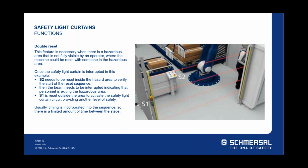So what double reset does is it requires you, after the light curtains are broken, to reset this function. You have to hit S2, which is inside the hazardous area. You have to leave that area, so the light curtain has to see you break those beams, and then hit S1 or restart 1 outside. This all has to be done within a time limit, typically within 60 seconds, okay? So hit reset 2, curtain sees you leave, hit reset 1. Now you can reactivate your system. Again, we're seeing more and more of this with these larger robot cells and larger workstations and work cells, okay?